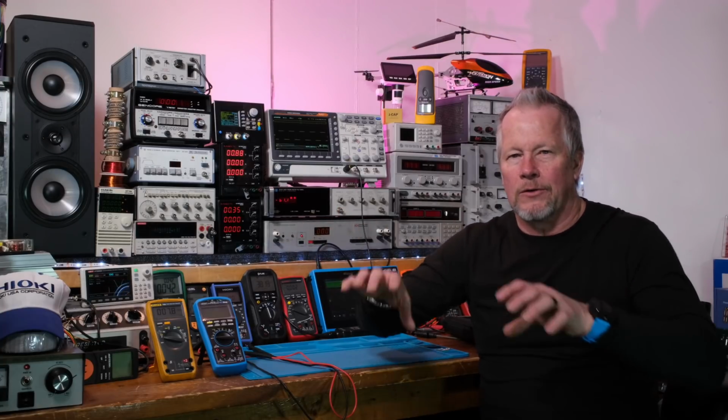So that's an advantage, because if you are isolating, say, digital ground and analog ground, and those circuits are operating on their own ground systems, you might not want them talking to each other and sharing currents. So you take them at one point, and that way you reference them to the same point, so they're not floating around from each other.